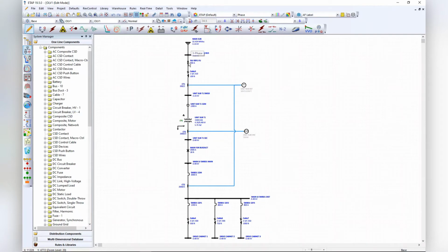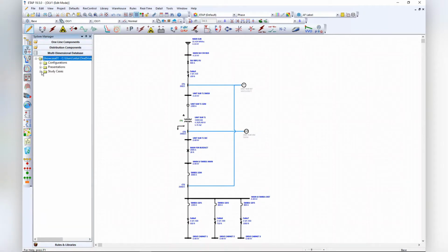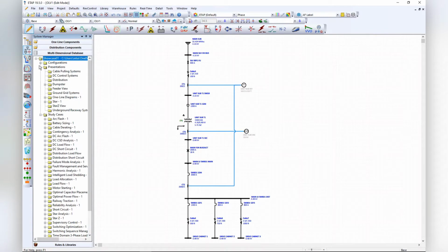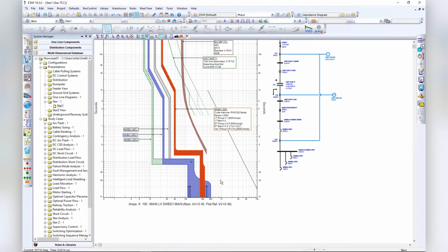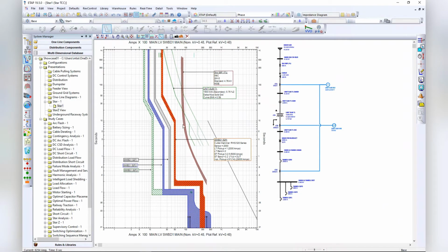the base case is just the fuse, and it's just the breaker with the typical phase settings on the trip unit, and I am going to pull, I hope I saved it. Yes, I did. So here's the standard coordination. It's just a standard phase coordination. The fuse is on the primary, and it's gonna allow for the main to trip first if necessary. This is the main in red, and then all the little feeders are downstream of the main,